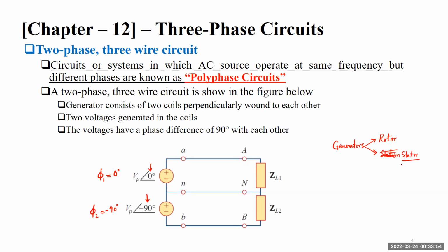So when the rotor rotates, and the rotor is a magnetic material, if a magnetic material is rotating in the vicinity of conductors which are connected to a circuit, there is a rate of change of magnetic flux across those conductors, and that generates EMF because of Faraday's law of electromagnetic induction. Once that EMF is generated, we can capture it and transfer it to our load with the help of these transmission or distribution lines. Okay, so this is what is happening here.